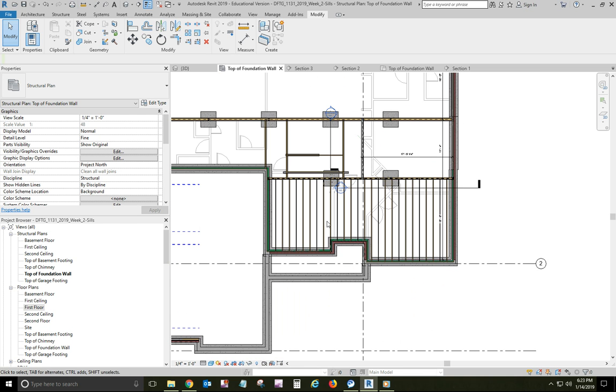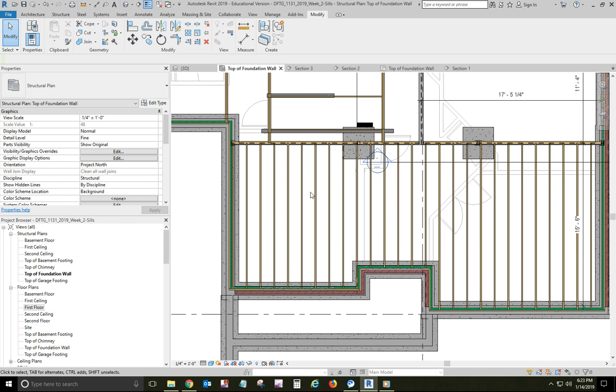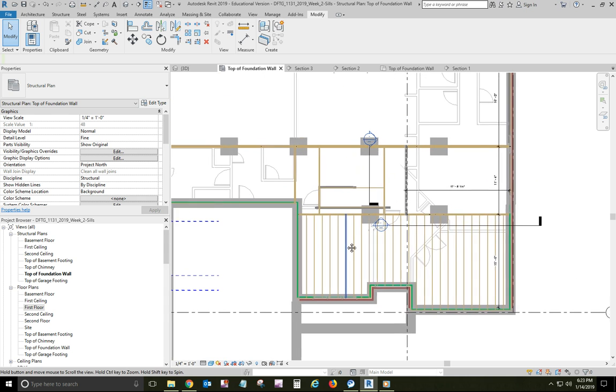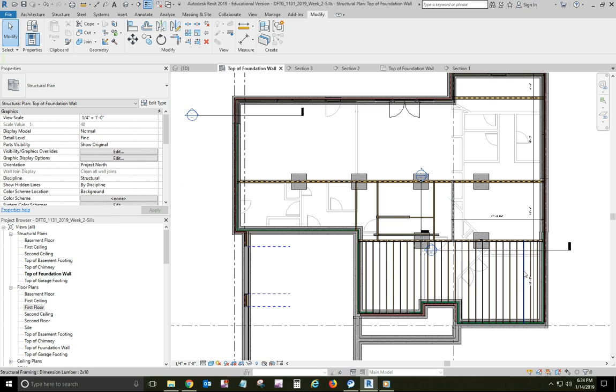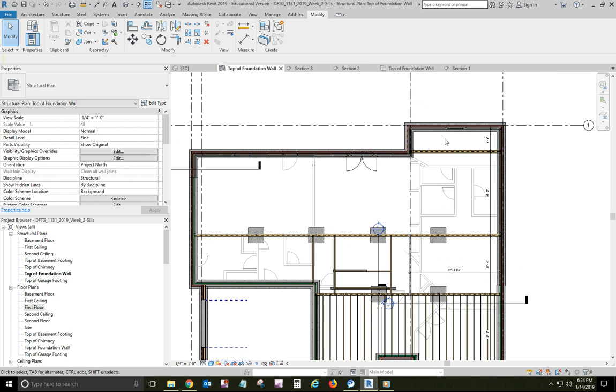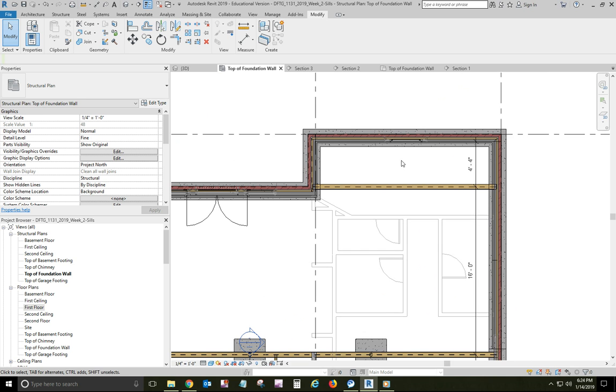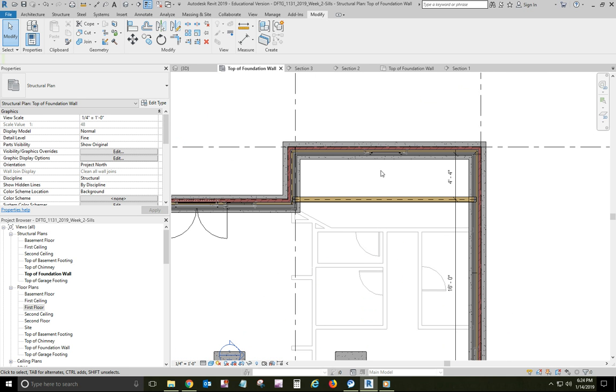Okay, the floor system. We're going to use a beam system to create these. We can create it, and then we have to come back and modify it. Now you're going to end up doing this in 4 passes because framing lumber is only 16 feet long, and they have to fit within our spans. So you're going to end up doing 4 operations of it. And I've got one done here. I'm going to demonstrate on this little bitty one right here just to show you the steps, and then you just have to repeat them, okay?